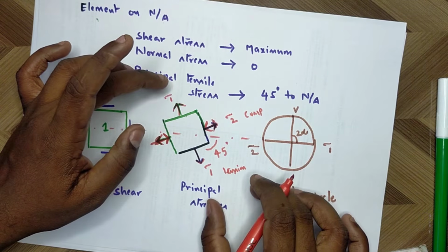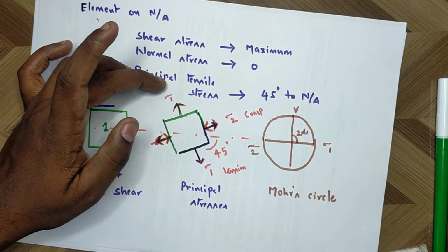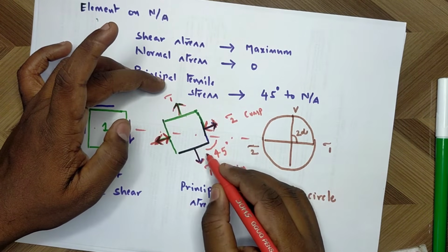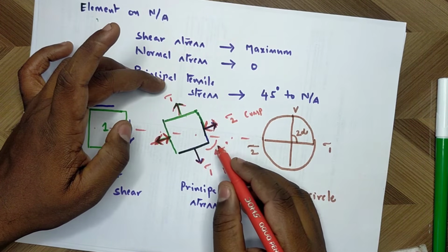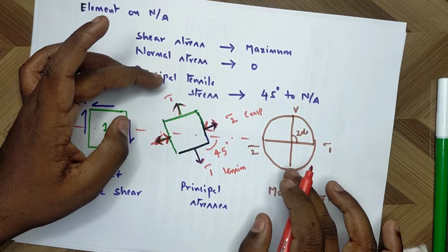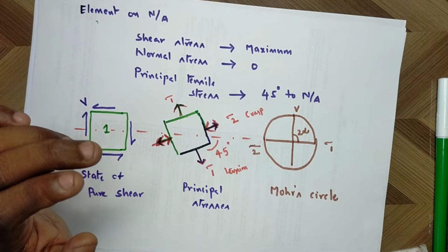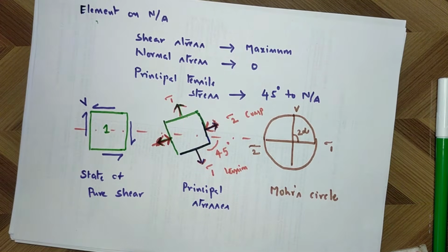That's why we achieve a state of biaxial tensile and compressive stresses. These principal stresses are at 45 degrees with respect to the axis of the beam. It is necessary to understand the principal stresses to understand the cracking of concrete.